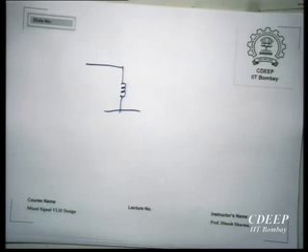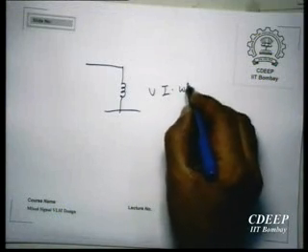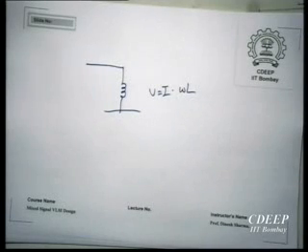what is the voltage across it? Omega L, right? If I is proportional to whatever, right? So for the same amount of current, the output will be proportional to omega. The higher the frequency, the higher its impedance, same current flowing through it, the voltage will be higher at higher frequencies, right? Voltage equals I times its impedance, which is omega L. So for a given current, it's a high pass by itself. So what I need is an inductor.